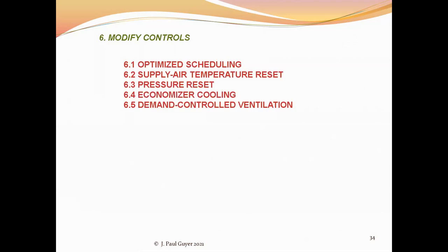And that is what is pushed through your fan and through the evaporator heat exchanger. But you're not exchanging any heat under these conditions, because the outside air is just right for the cooling that you want to accomplish.